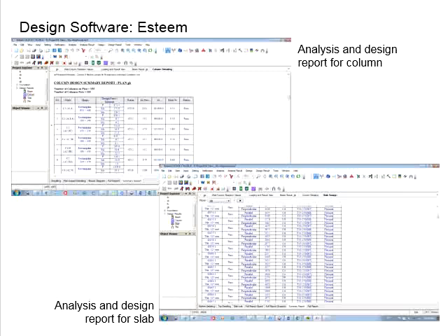Spend some time to do some random checking from manual calculations or with your Excel spreadsheet to confirm the design. Based on what you understand, the design outcome should be similar to your manual calculations. If you are using the same set of data input, in accordance with the same code of practice, namely Eurocode or BS, the output should be more or less the same. And this is the way that you can do some verifications.